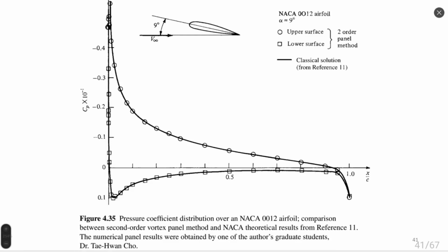And also another limitation, do not forget that such a method can be used for small angles of attack, which have no flow separation. So it can be used for airfoils, cannot be used for a flat plate, because for a plate we have flow separation immediately when the angle of attack is not zero. And because of this problem, I see nobody else answered the question, but okay. Because of this problem of flow separation, CFD is always preferable.